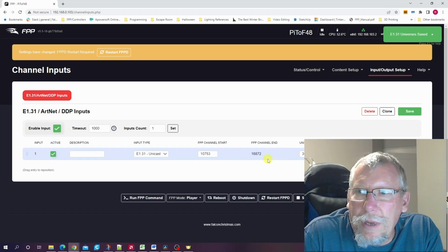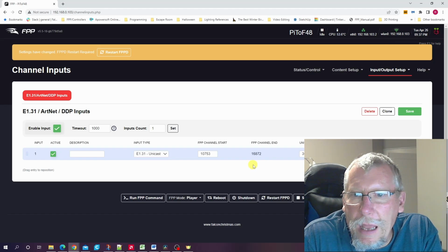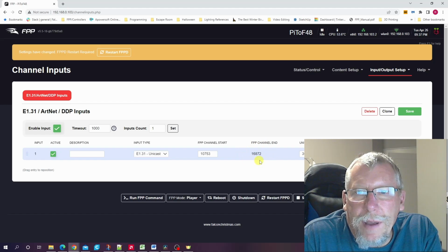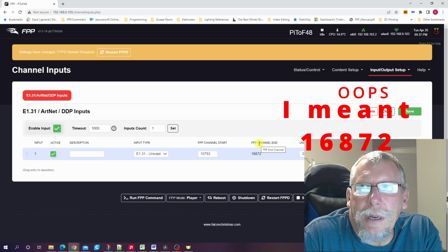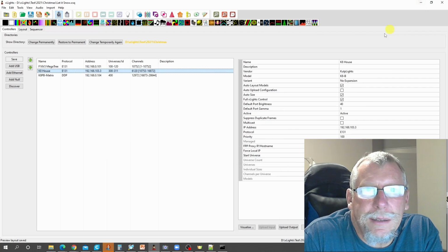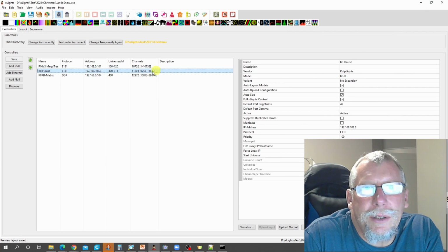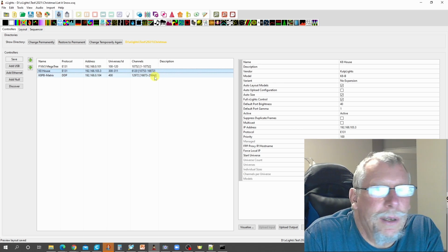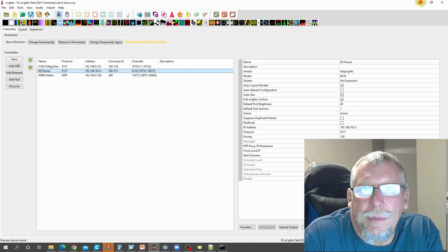So once you have that, save it. It'll ask you to reboot. And if you look, it's going to give you an end channel here. So you want to verify that that's correct. So that's 16872. So let's go back and make sure that it matches what xLights has. 16872. So it matches. So you got the configuration right. So that's how you would configure the input in that situation.